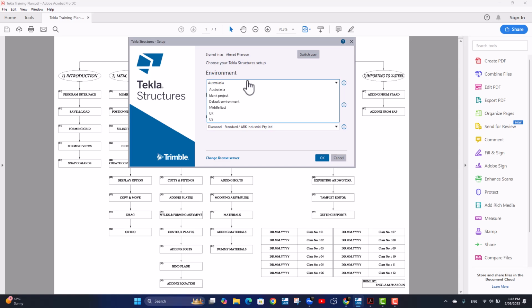The European catalog is completely different, because it just has some types of I-beams, which depend on the ratio between the flanges and the web. For example, for the IPE, the flange is half the width. Take IPE 300: that means we have a web size of 300 mil and a flange size of approximately 150 mil. What about the Middle East?